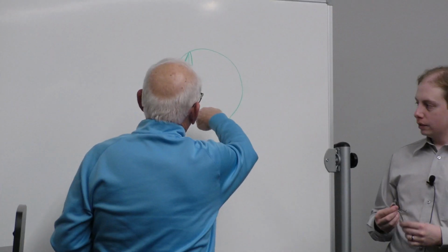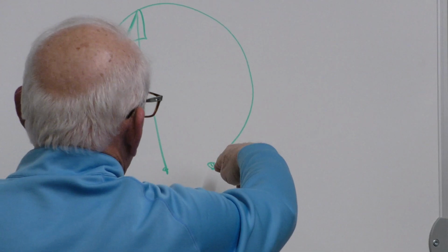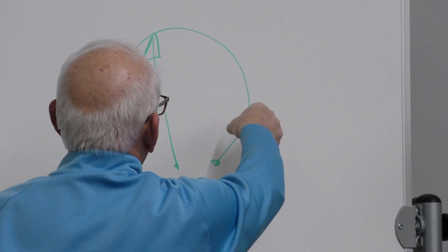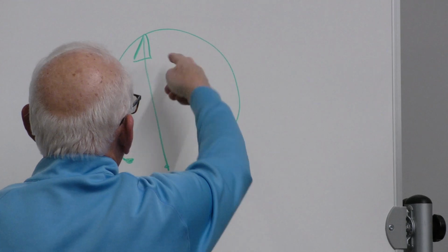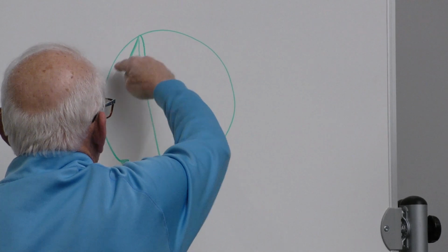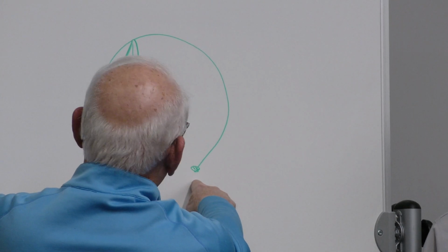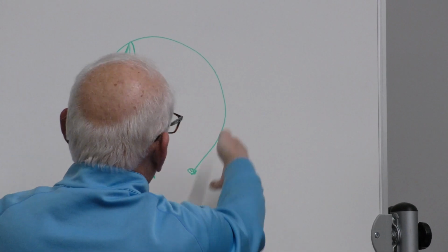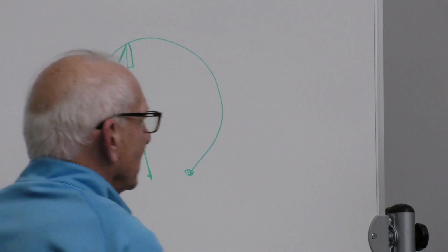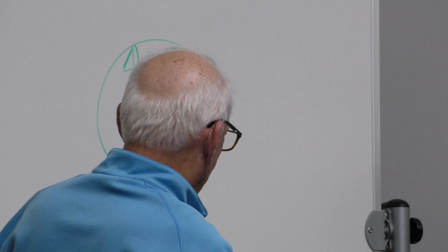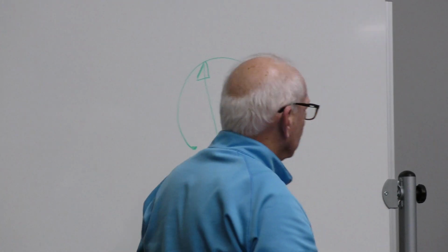But quite often, in a practical sense, in a circuit, that's called a wiper. And this is the increasing resistance. So if you think of this as a resistance wire, it means a material that increases resistance as you go around. As you turn the center, you decrease it to 0. You can get resistance by putting 2 leads here, or you can do 2 here. Sometimes you want to decrease something while you're increasing something else. Okay, so it just gives it more functionality for you.